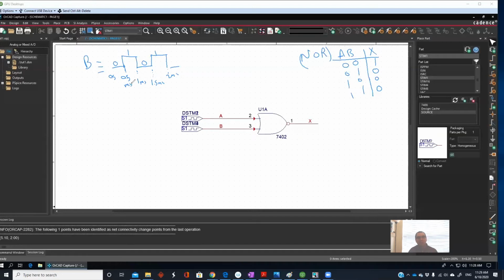So what we are doing here is specifying the signal. And now we're going to learn how to specify it here for the two inputs. A has, as you see here, a slower frequency. B changes 0, 1, 0, 1, while this one goes 0, 0, 1, 1, so it's a slower frequency.